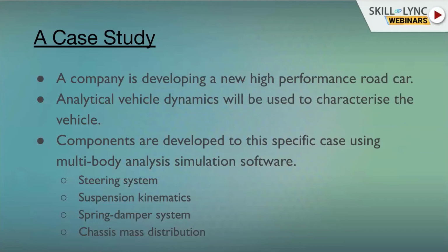And from that, the vehicle will be subjected to various simulated tests, such as constant radius cornering to understand what the vehicle's lateral acceleration capacity is. Things to understand steering. So you'll input various things like step steers or sine wave inputs to the steering system to understand how the vehicle scores in control and stability.